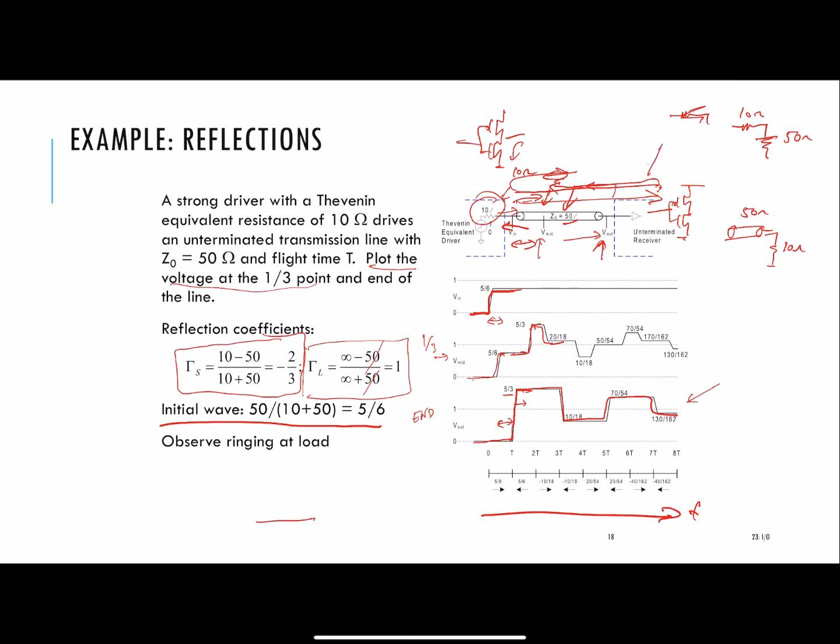If you just put your probe here, that's pretty typical. You won't see this. You'll see some nice ringing like that. And that's indeed these waves going back and forth, back and forth, creating this ringing structure. So now the problem is, until this whole thing is settled, you can't launch your next bit into this thing. So you just have to sit there and wait for this ringing to go away before you launch your next input.